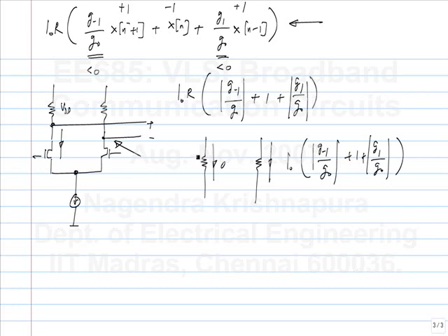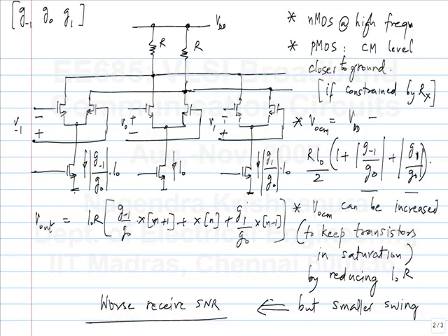So whether I do it with a single differential pair or any number of differential pairs, I cannot avoid this, simply because I have this much signal swing. The maximum value of this is this one, and the minimum value is just the negative of that. And this happens with the right combination of bits, when the coefficients times the bit all add up, either in the positive or the negative direction. So that much current I have to accommodate, and to accommodate that much current, I have to drop a certain voltage across these resistors. Is this clear? Okay.